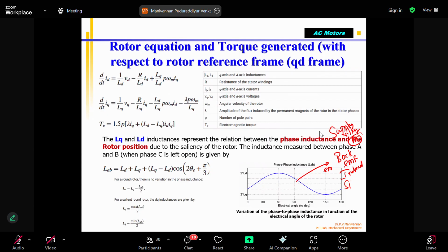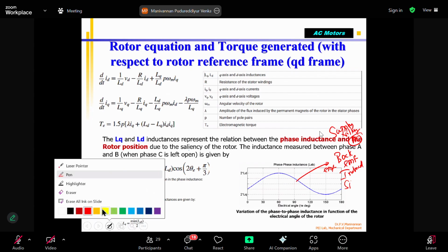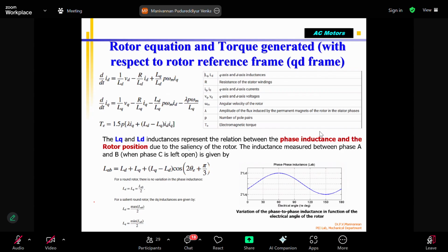Apart from that, you have a permanent magnet which you are rotating. Initially, you rotate the synchronous motor. You have to rotate this so that it cuts the stator coils, and in the stator coil a back EMF is produced. The back EMF will be sinusoidal in shape if the winding is uniformly distributed. We know the two types of windings. With uniformly distributed stator winding, you supply a sinusoidal AC voltage, and the magnetic flux generated and the back EMF generated will also be sinusoidal like this.